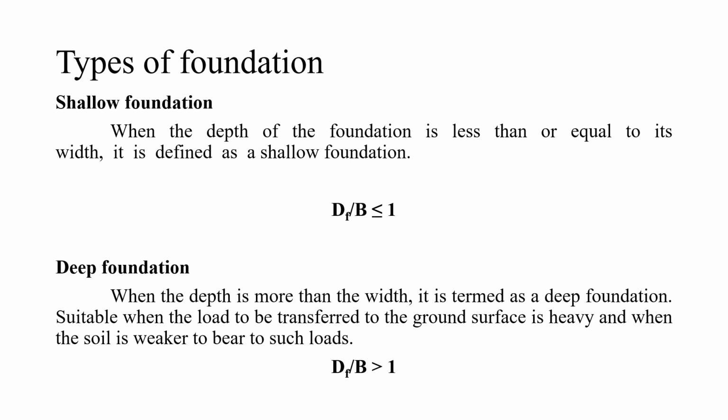Foundation can be broadly classified into two types. One is shallow foundation, another one is deep foundation. As per Terzaghi, if the ratio of depth to width of the foundation is less than or equal to 1, then it is called shallow foundation. If the ratio of depth to width is greater than 1, then you call it a deep foundation.